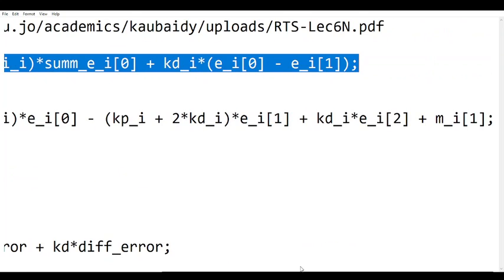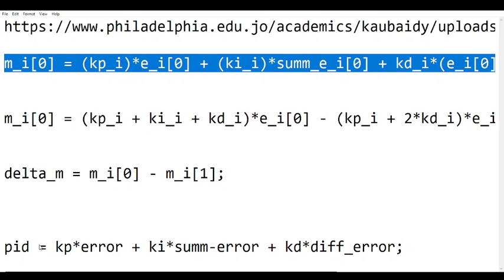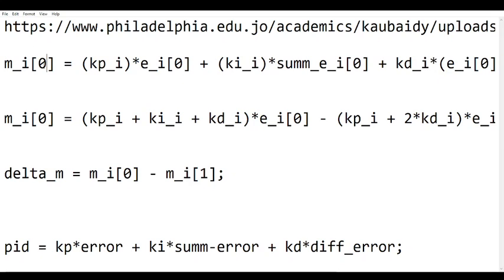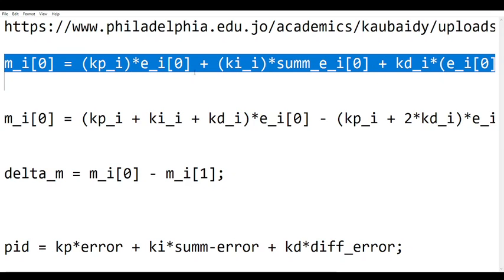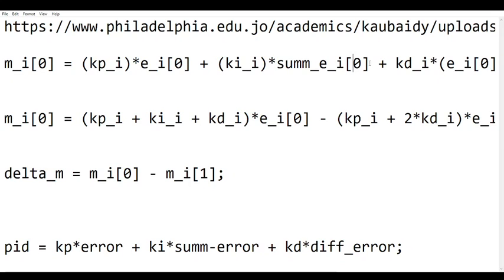So let's say you have a system where you're ramping up the input power slowly. The position form would absolutely not work for that, because by the time you get to a point where your converter can get to the set point, it's racked up so much of this particular value, it's ridiculous. It's going to take forever to come down.